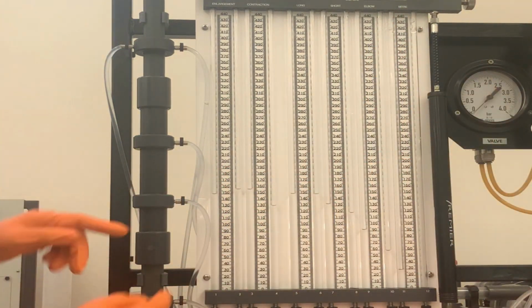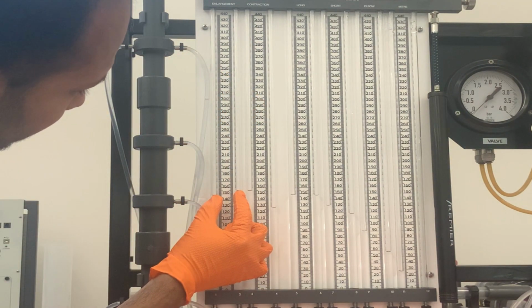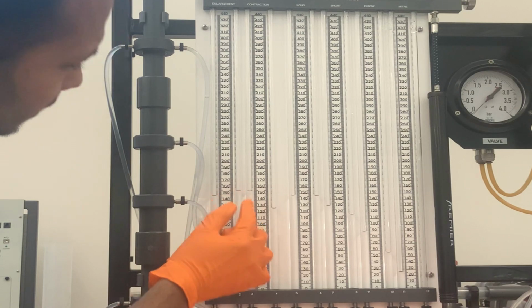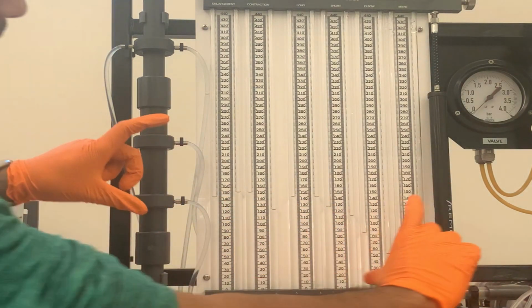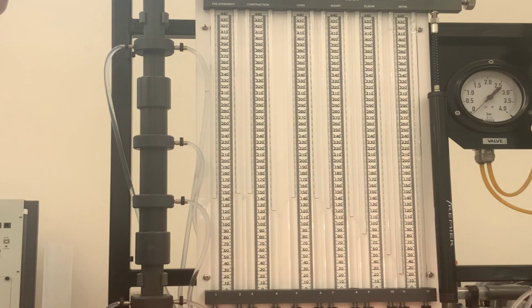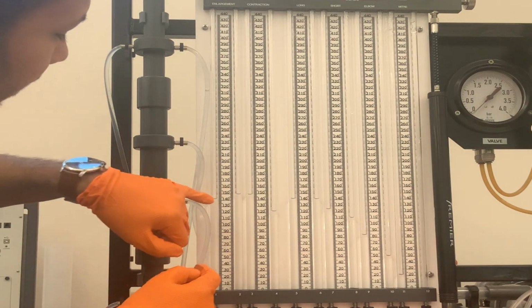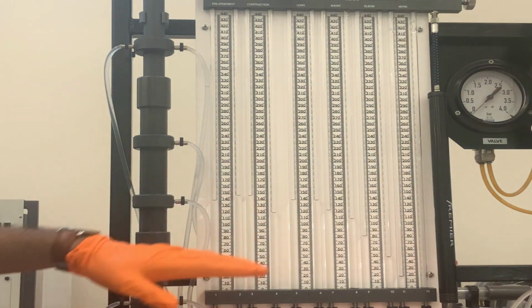So all I have to do is take the reading between these two. So you see, if you take the reading between these two, sometimes you will see the water level is dropping. What you can do is take a picture of an instant and take the differences. So all you have to collect is the head difference, maybe H1 and H2, and take the difference at any instant.